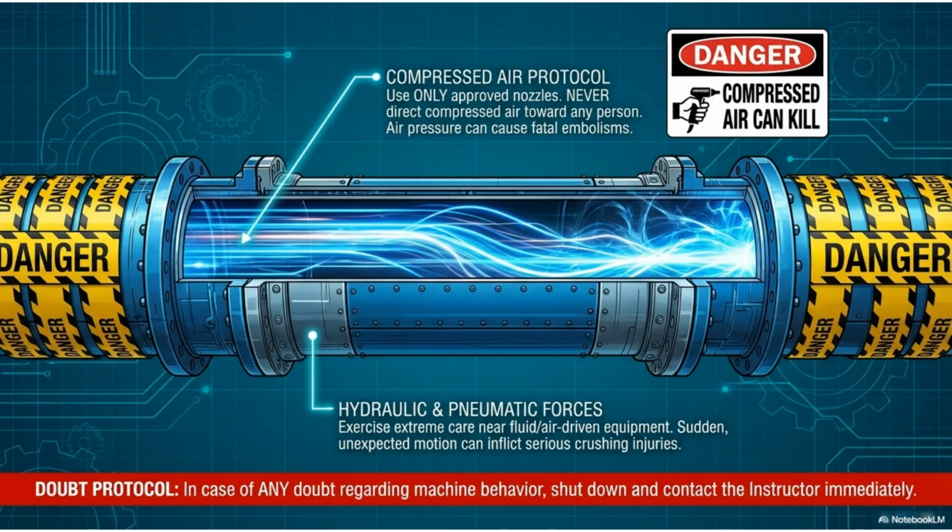Compressed air protocol. Only use approved nozzles and never direct compressed air toward any person, as air pressure can cause fatal embolisms. Exercise extreme care near hydraulic and pneumatic equipment. In case of doubt, shut down and contact the instructor immediately.